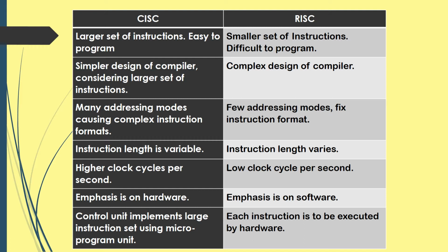In the 70s and early 80s, designers started looking at simpler instruction set architectures. So a very small set of instructions, and certain designs, that is one cycle execution time and pipelining, and considering the number of registers, the instructions were defined. Few data types, very simple addressing modes, and as far as the architecture is concerned, the Harvard architecture. RISC designs often use a Harvard memory model where the instruction stream and the data stream are conceptually separated.